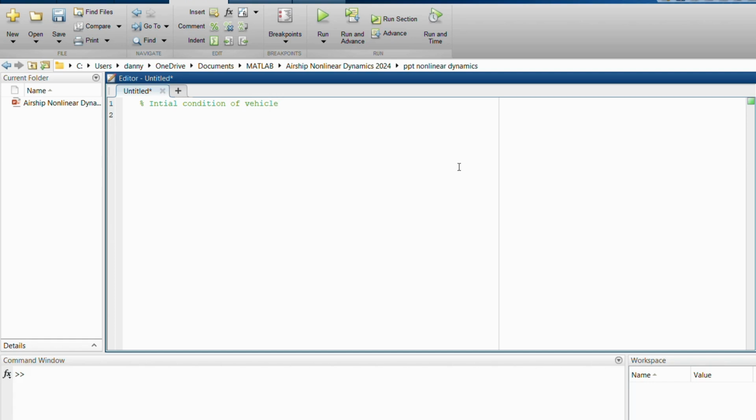So first we need to define the forward velocity, backward velocity, and all three components of velocity. So basically the initial velocity in u direction. Since it is initial, we are defining it at 0 because time starts from 0. So for the initial condition we are defining u naught as 0. Suppose we are giving the velocity 10 meters per second, and we need to write the semicolon to stop printing in the command window. Now we have velocity component v, say 0, w naught, say 0. Now we have defined the initial velocity components.